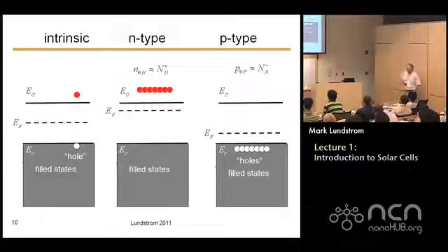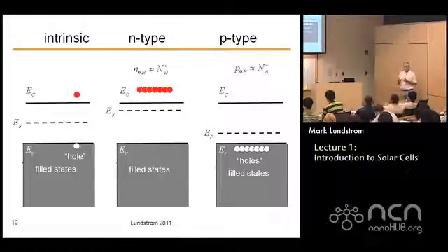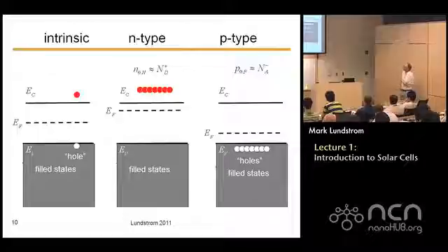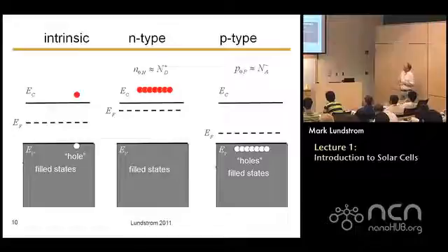Okay, all right, and then just to acquaint you with some basic terminology in semiconductors. If we just have pure silicon, and silicon these days is probably the purest material that human beings make. It's been refined to enormous precision, very small densities of defects. If we take an intrinsic pure piece of silicon, ideally we shouldn't have any empty states in the valence band, and we shouldn't have any electrons in the conduction band.